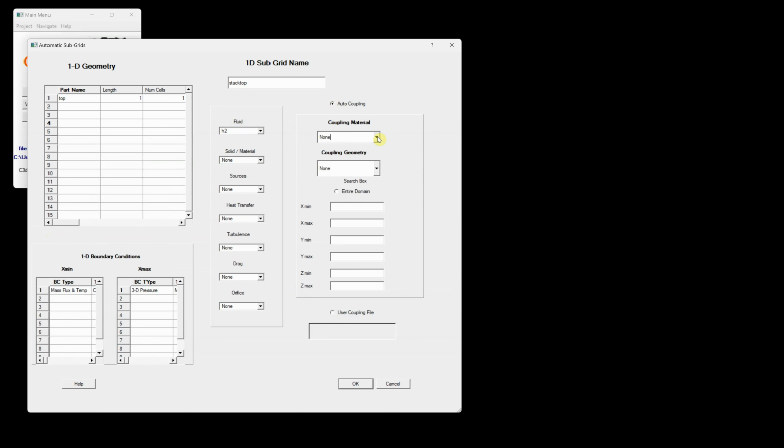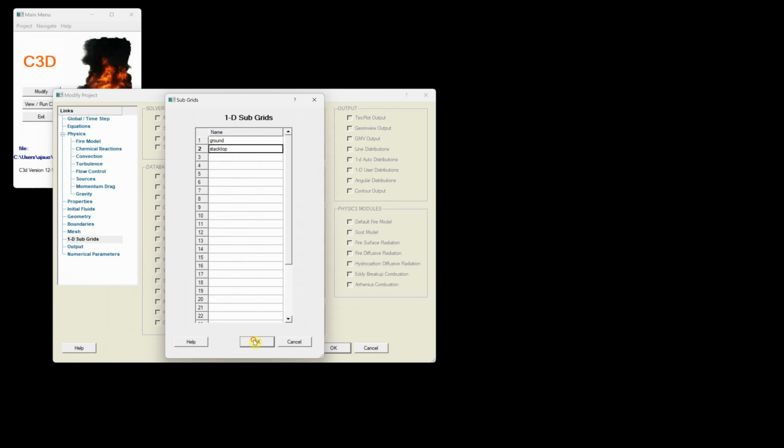Okay, now we have to couple it. The material, we built it out of insulator 2, and we're going to use 0 so it searches over all of the X, all of the Y. Now we want to locate just the top surface, so do 14 point, remember it's 15 meters high, and 15.01. So the top of the stack is exactly 15 meters, so those two Z dimensions will grab that top surface. Okay, we're done here.